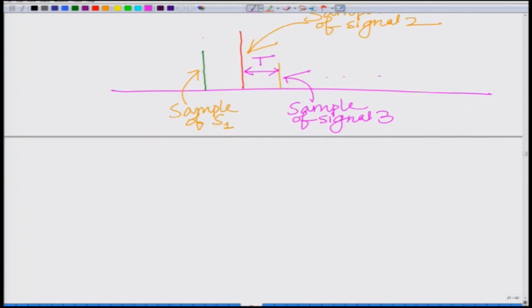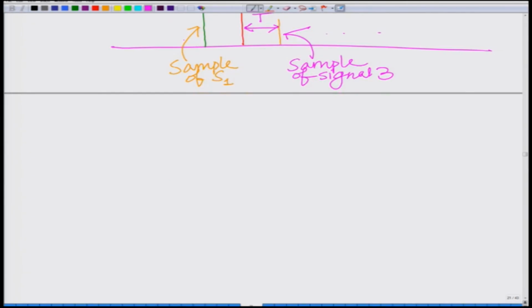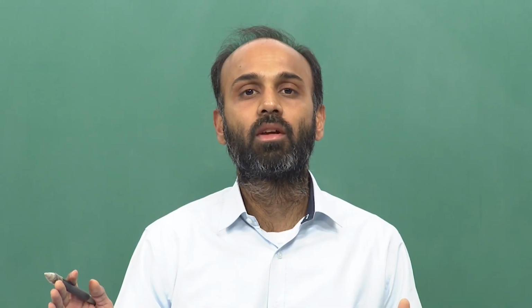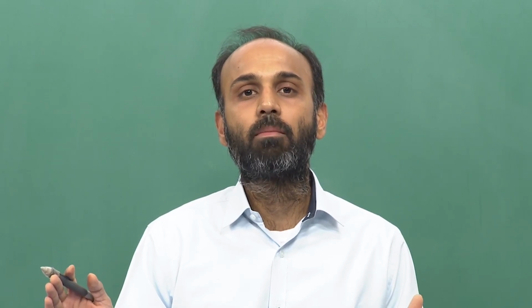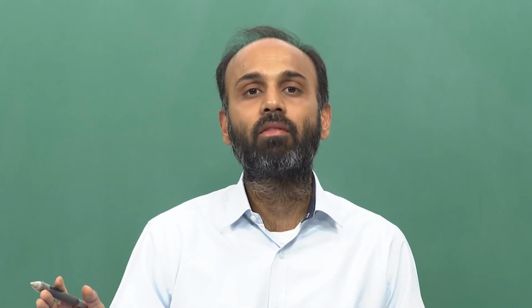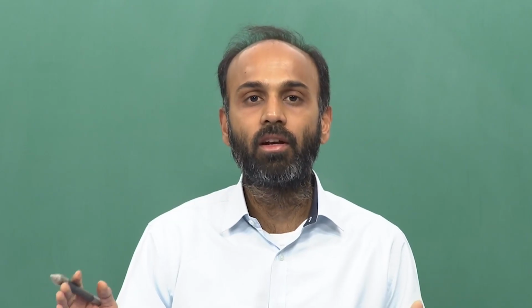Now we have to note that the sampling duration of each signal is uniform, that is Ts, which means every signal has a single sample in Ts. Therefore n signals will have n samples in the interval Ts.